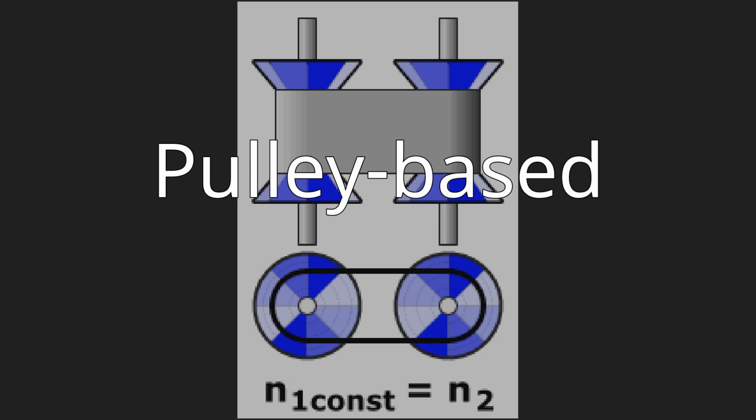Each element of the chain must have conical sides that fit the pulley when the belt is running on the outermost radius. As the chain moves into the pulleys, the contact area gets smaller. A belt-driven design offers approximately 88% efficiency, which, while lower than that of a manual transmission, can be offset by enabling the engine to run at its most efficient RPM regardless of the vehicle's speed.